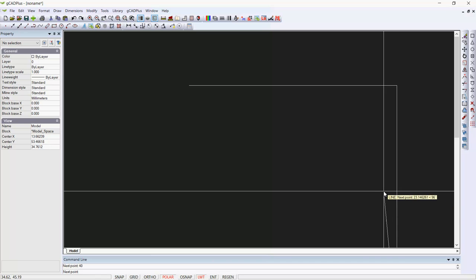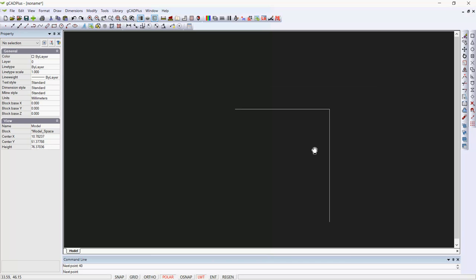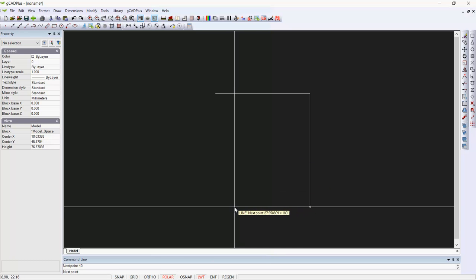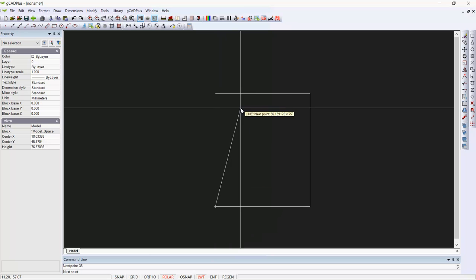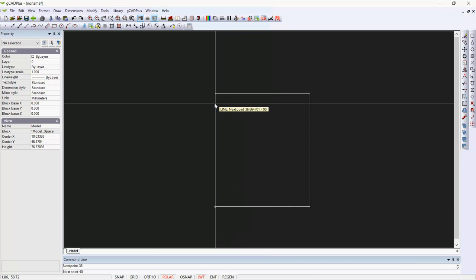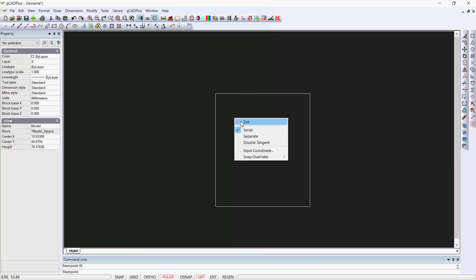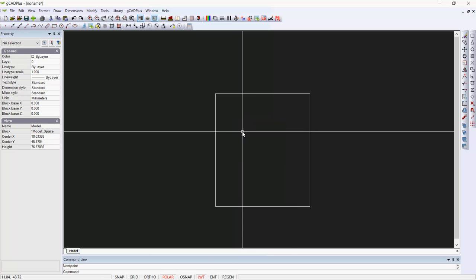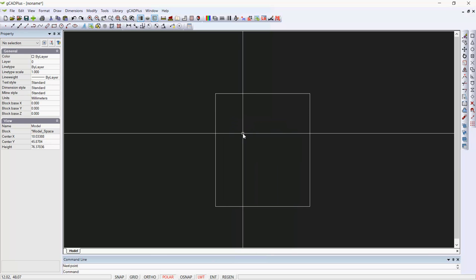in that direction. I'll need to use the wheel of the mouse to zoom out a little, and we come across back in this direction 35 feet, and we can then go 40 feet in that direction. Just make sure you move your mouse so that the cursor points straight up, and exit from there. So we have a building of the appropriate size.